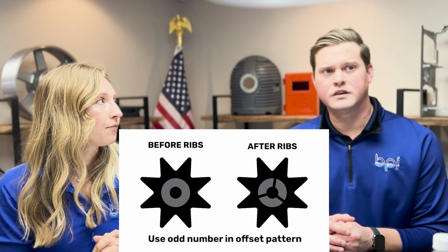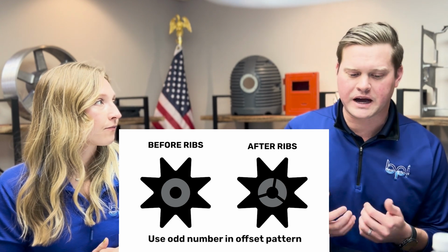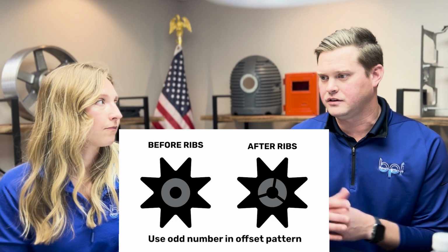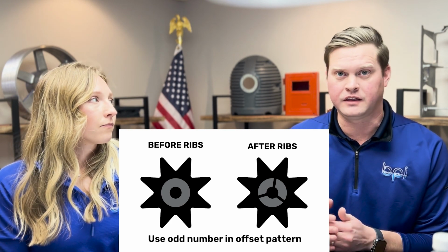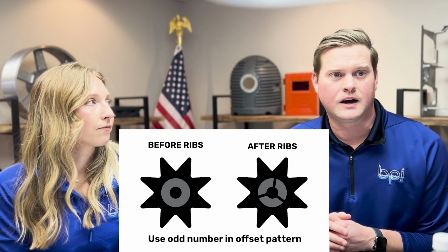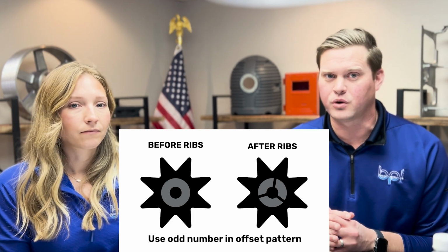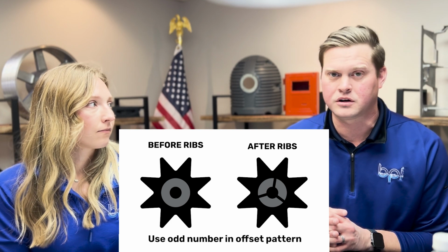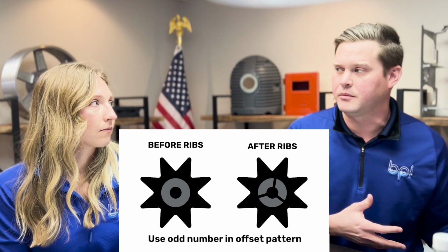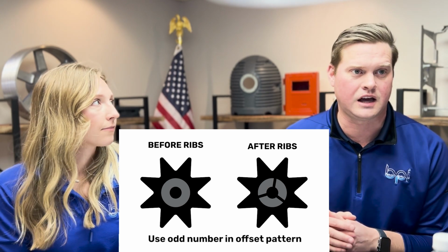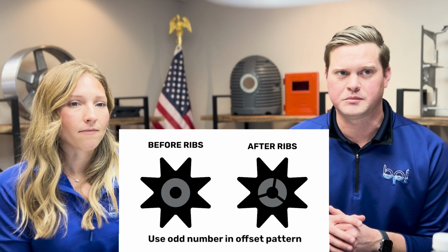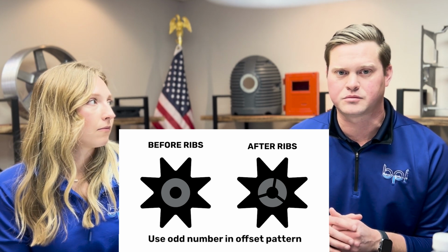Yeah, and I think if we go back a couple slides where we talk about the wall thickness, it really allows you to have some of that complexity without adding that additional cost of a thicker wall, which means more metal, which means more cost. So very important to keep in mind as you're designing your part. Again, do you want a good casting coming out? Does it need to be permanent mold? Does it need to be die cast? Does it need to be sand casting? But keeping ribs, fillets, that type of stuff in mind as you're designing this process here. Yep.